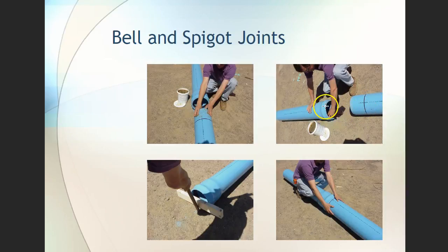When you slide it in, that point right there seats right at the bell. So that's one of those fail-safe things. This size pipe you can actually put together fairly easily with a pry bar and a 2x4 on the end of the bell. You line it up straight, and you push it together, and it's a very positive seating feeling when it hits in. Again, it goes in roughly, depending on the size of the pipe, about 6 inches on this size.